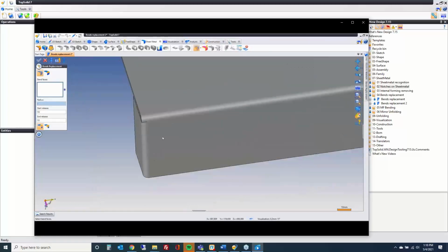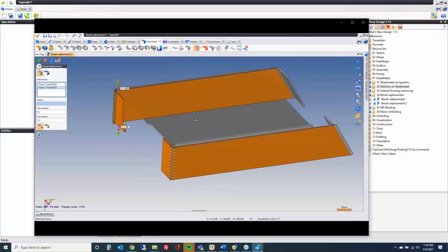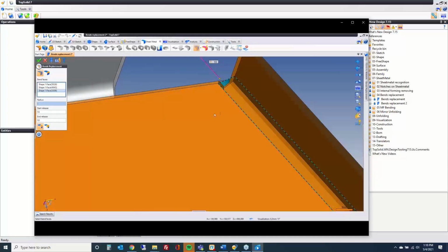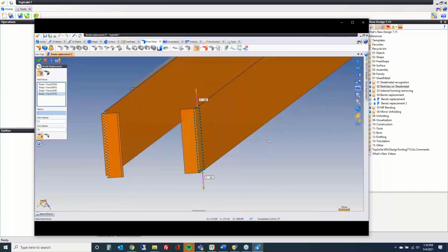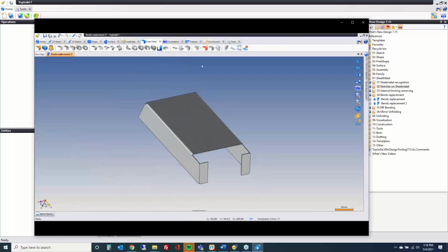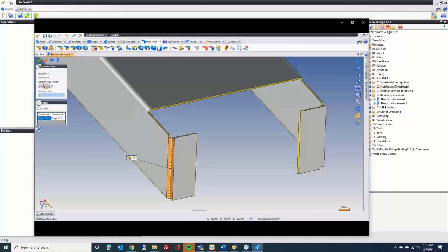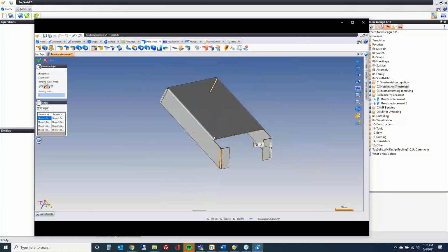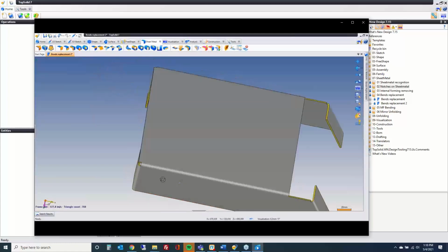Let's take a quick look at it. So we're going to start removing bends again on this imported part. You can see how that bend is kind of weird on the corner. And so here we're just trying to process it so it's designed properly. And then we can go in, recognize the sheet metal part, and then we can add the bend radiuses back in. TopSolid cleans up everything perfectly. Notice it found all the edges automatically as well. It's kind of cool. And you're done.